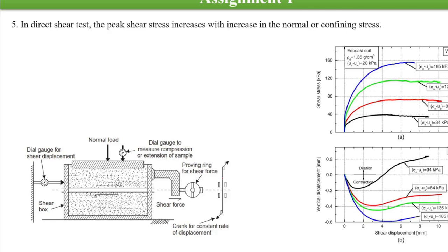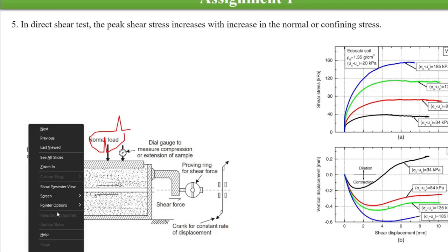There's a shear box, where we place two samples and we make one interface in between the samples. We try to provide the shear force in the sample to calculate what friction is there. So we basically calculate the c and phi values. Before that, we also apply a normal load on the sample. That is shown here. So we also apply a normal load here.